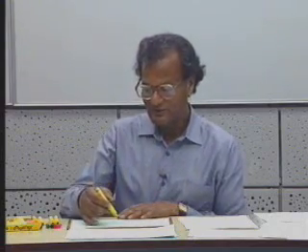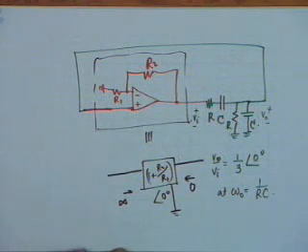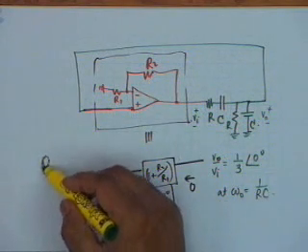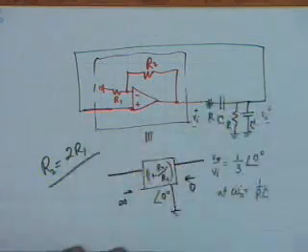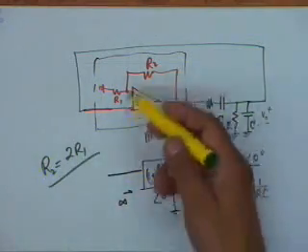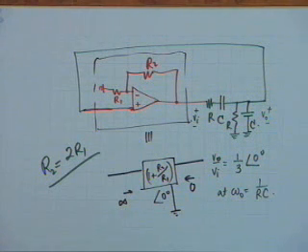Now can you tell me what should be the value of R2 in relation to R1? Obviously for these to oscillate, R2 should be equal to twice R1, and this circuit contains 4 resistors, 2 capacitors. You can make it in the laboratory in 10 minutes, and you can see beautiful sinusoidal oscillations. One op amp, you take a 741 and make connections R2 and R1.